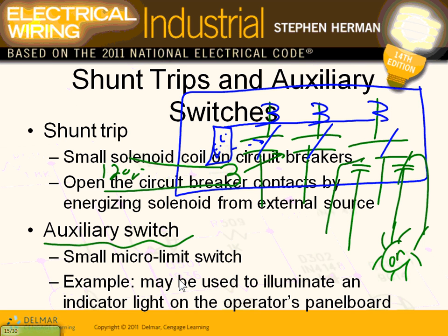You go higher than 200 amps, or 3-phase 480, guys, and 225 amps, they start using them as a controller, almost as a controller. As a matter of fact, medium voltage circuit breakers are used as a controller, Chris. When they turn a medium voltage motor on and off, you know what they do? They don't have a magnetic starter on the wall. They have a circuit breaker that you push a button, close it, now the motor is running, push a button, open it, the motor stops. The circuit breaker, no contactor.